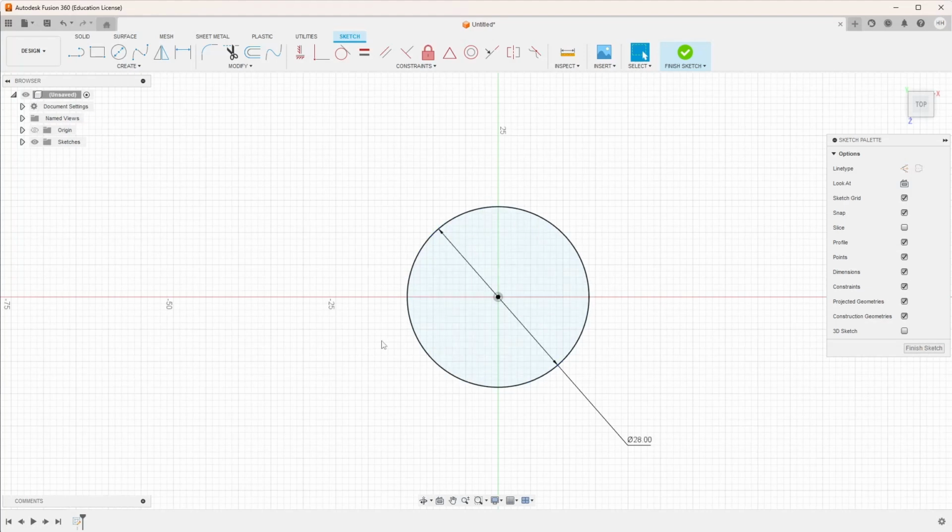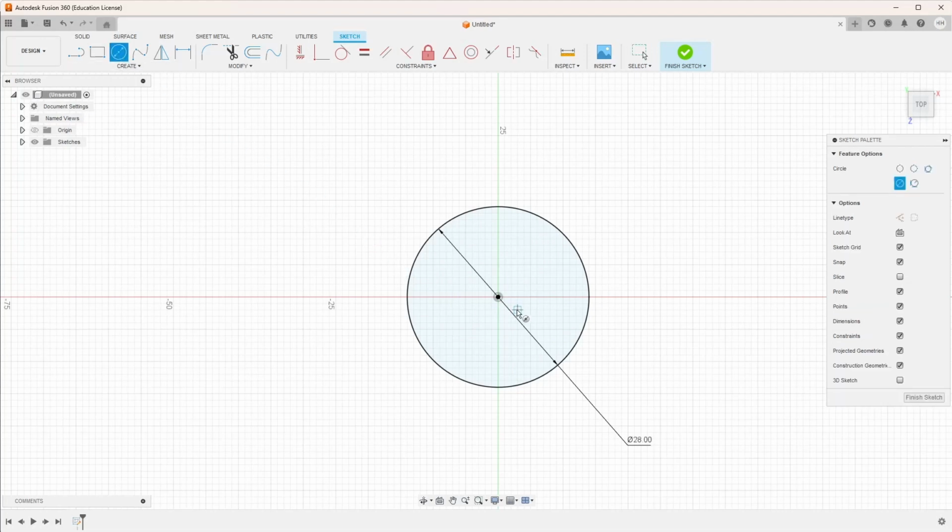So our F1 car is going to have a round wheel that's 28 millimeters, and I need to design a pivot point or something in the center for my wheel to move. So what I think I'm going to do with this particular wheel is I'm going to put a hole here in the middle, and I'm going to allow a carbon fiber axle to be pushed into the center of this and maybe glued into place. Okay. And if I had a carbon fiber axle that I wanted to use of, let's say, 5 millimeters, I could put 5.